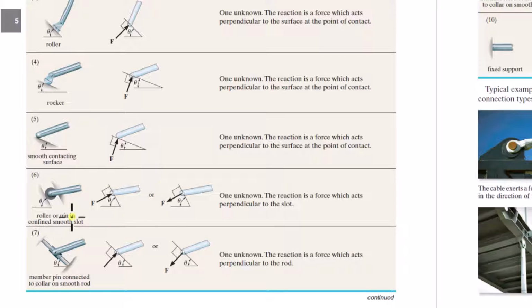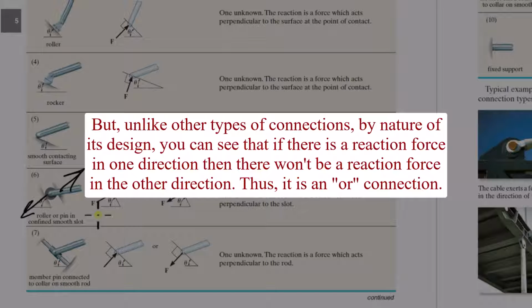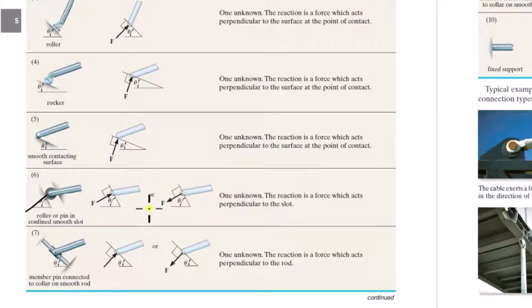It's just saying that, like how we talked about how there are some components like a pin connection where it's not designed to support a rotation. What this is saying is that this is designed to support a force. It's designed to prevent rotation or movement, translation, in this direction or this direction. That's what it's saying. So this type of support is designed to support either one of these loads, but it has a pin here, so there's no rotation it's preventing.